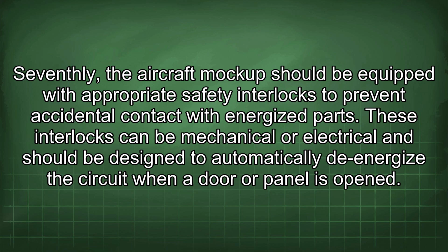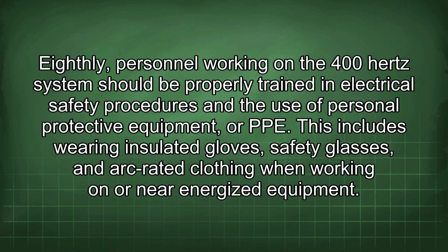Seventhly, the aircraft mock-up should be equipped with appropriate safety interlocks to prevent accidental contact with energized parts. These interlocks can be mechanical or electrical and should be designed to automatically de-energize the circuit when a door or panel is opened.